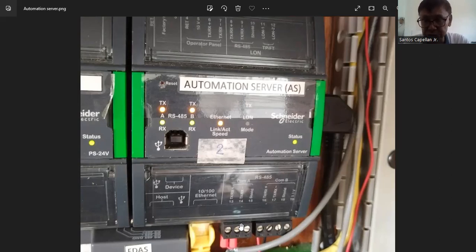Okay. So this thermostat, of course, you have to coordinate with the mechanical supplier. You have to tell them, okay, you have to supply something that I can easily integrate with my BMS. So meaning you can recommend, okay, I'm using BACnet MSTP. Maybe you can supply a thermostat that is capable of communicating with that communication protocol. So they have to conform with that one.